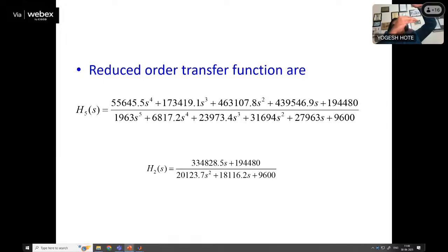So as we go to 8th, 9th order, the matching will be very, very high. But it depends, because if you take a 9th order model, there is definitely a risk, and you also require more solution time and the control size will be higher. So it is a trade-off, whether you require less solution time or better performance. That trade-off should be there.